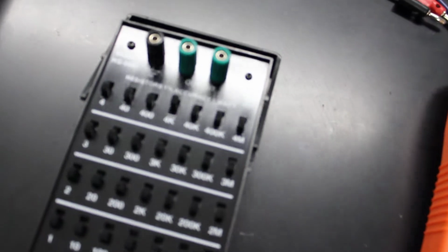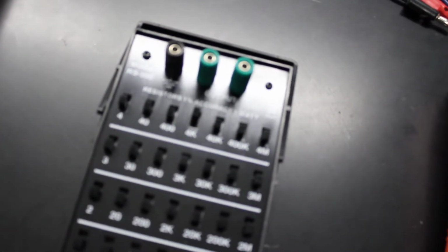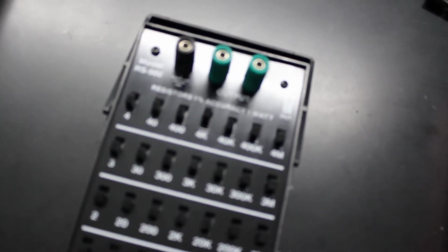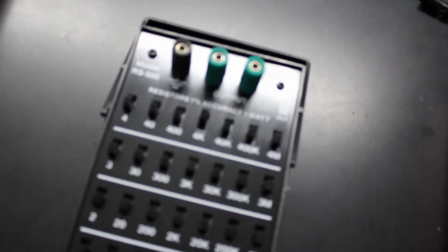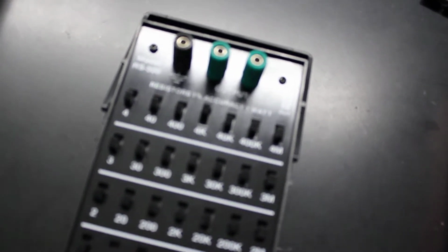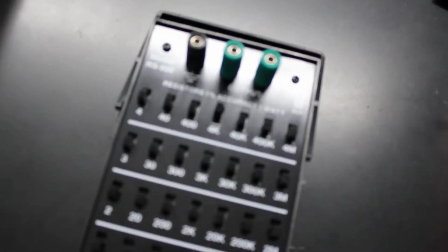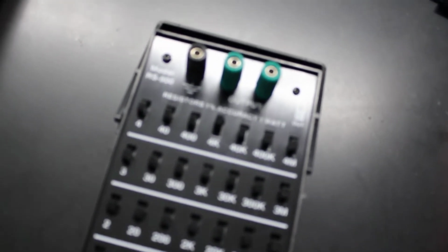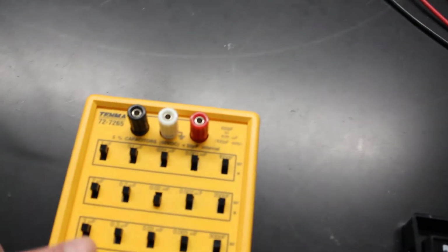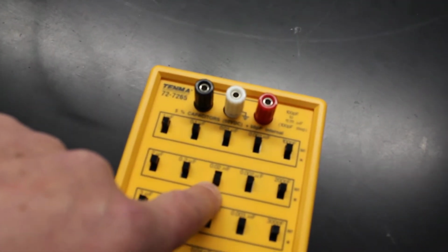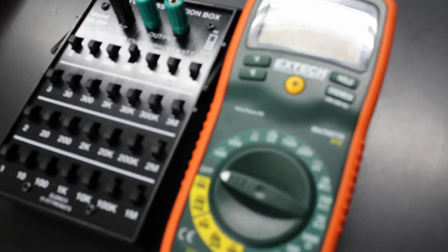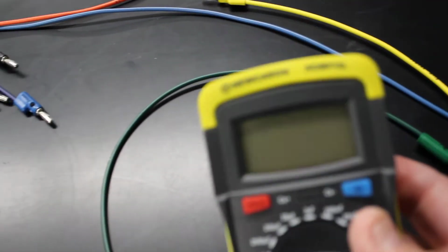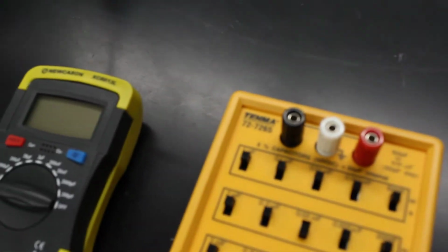And I've done the calculation. So omega is 1 over RC. I've chosen R to be 4,000. Omega is 2 pi f. I've chosen f to be 2,000 hertz. And when I do the calculation, which you should repeat, I get that the capacitor should be 0.02 microfarads. And so I have that switched on here. Over here I have a multimeter that I can use to measure precisely what the resistance actually is. And I also have this capacitance meter which I can use to measure the capacitance of the capacitor.